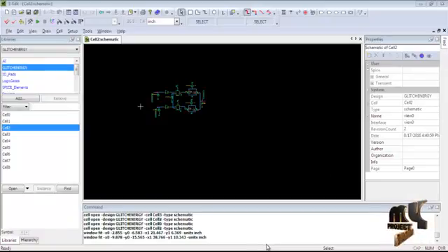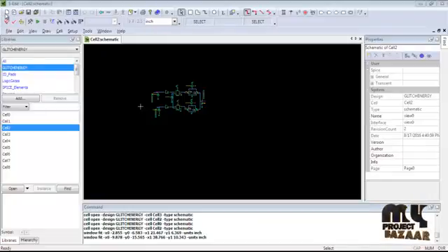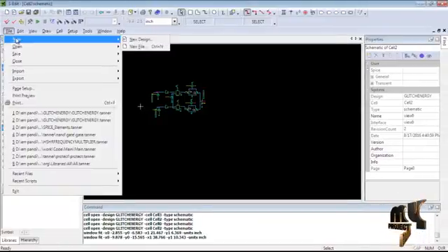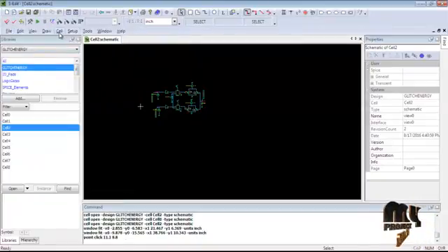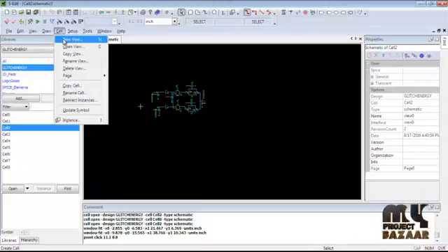Next, we see about the running process of our product. Our product is done in CMOS technology using the Tanner EDA tool. This is the Tanner EDA tool, a special SPICE simulation tool. First open the file and select new and new design. Now the window is open. Then we select the specify cells, for example cell 0, cell 1. First create one cell. That cell is cell 0.